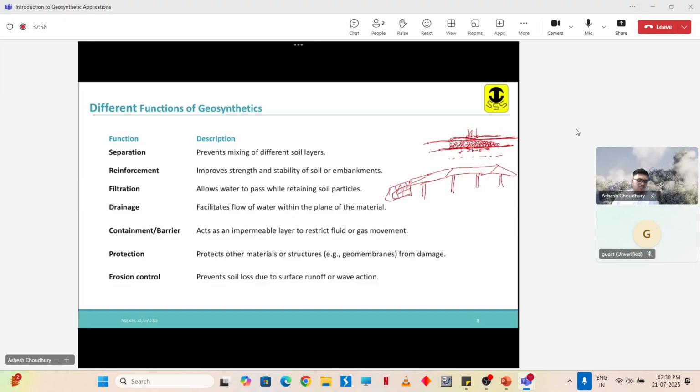So for this purpose, to construct this approach area, instead of making piers, we construct a reinforced earth wall. We reinforce the soil so that we can construct an approach road over it. Or else, say we want to construct a steep embankment. Generally, with the available soil, you are able to construct an embankment like this.